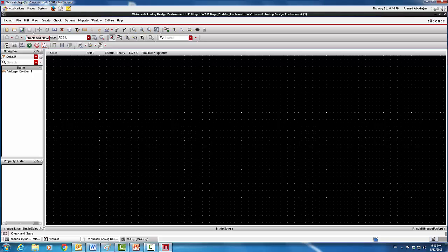When you save, check basically means save the content and check if I haven't made any rules mistakes, like if I have resistors not connected or a floating node or something, then it will show me an error here. So this is important. When you save the circuit, it is going to check. If you know that you haven't finished all the drawings, you can just save it here.